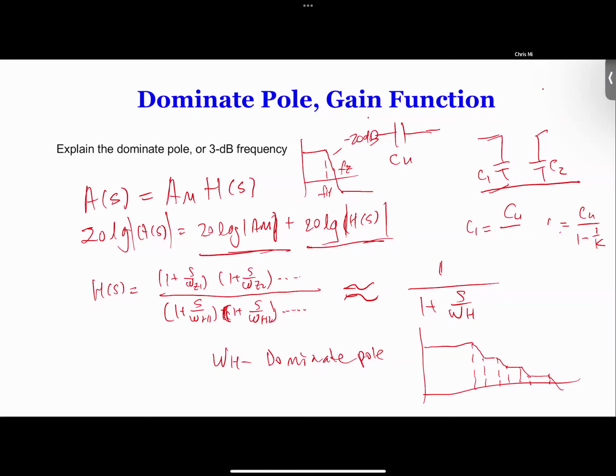Right? Sometimes you might actually have poles and zeros overlap. Like you have squared, let's say 1 plus omega over 100 squared, which means you have 2 poles or 2 zeros at the same point. So what that tells you is, if you have 2 poles at this point, from here to here, how many dB do you think you can get on the drop per decade? It's going to be a 40 dB drop. If you have 2 poles at some point, it's going to be a 40 dB drop. Okay.